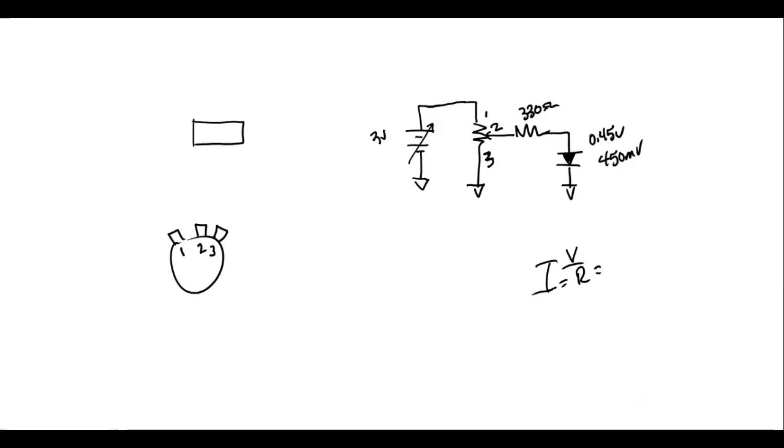So that's what we're doing. Right here, we're measuring the voltage drop across R1. You see that in your table, right? And we know the size for R1, right? You understand that? Yes or no? So all I have to do is take what? To calculate I, I'm going to take the voltage drop across R1 that I recorded in my chart, and then divide that by 330 ohms, and that will give me I through the diode. Why is that I through the diode? Because they're in series with each other. And the current is the same in a series circuit, right? So if I calculate the current flow through my resistor, then I know the current flow through the diode.